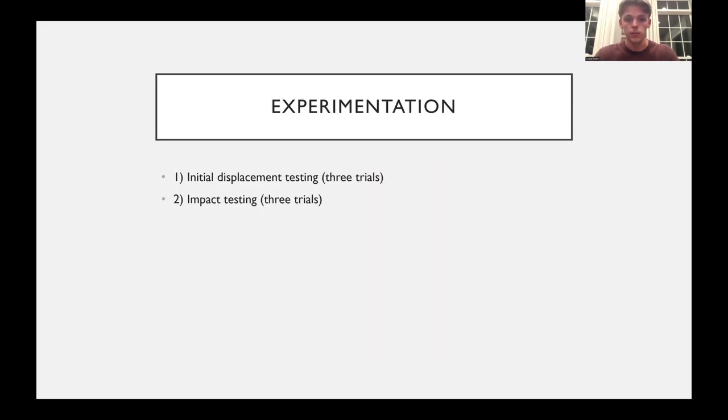For my experimentation, the first step, just as in Lab 3, I displaced it with an initial displacement of about 20 millimeters, and then I released it while collecting data. So I waited about 0.8 to 1 second before releasing it.